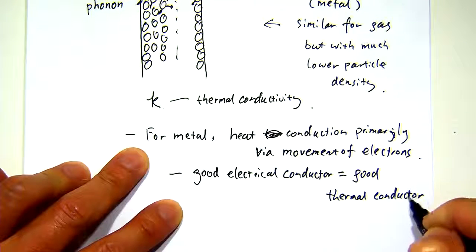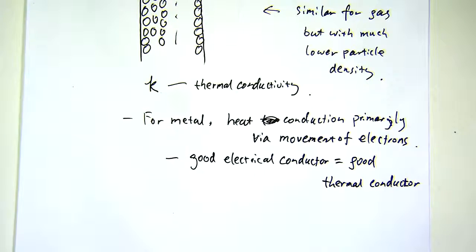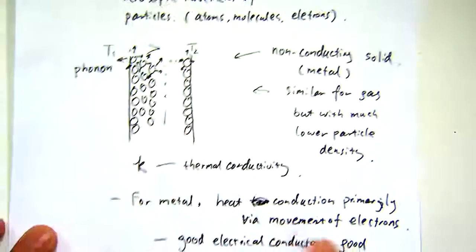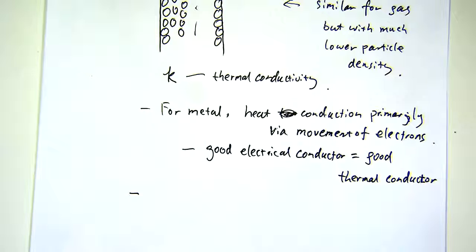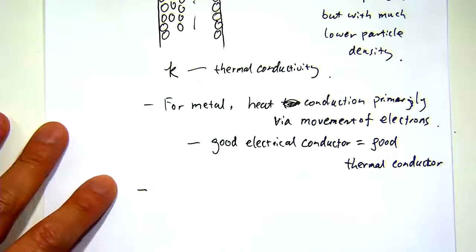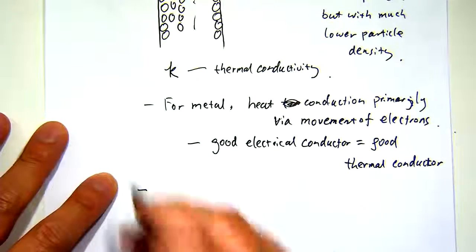And we can say that's mainly because the mechanism is that the process happens via the electrons. But in thermal conduction, you don't have current, right? The thermal conduction is via electrons, but the electron is still localized. You don't have a flow of electrons across the medium. So that's why you don't have electric current. So basically there are two types. Solid non-metal will be via this type of mechanism, and metal will mainly be through the electrons. There is one special material which is not metal but has very high thermal conductivity, which is diamond.